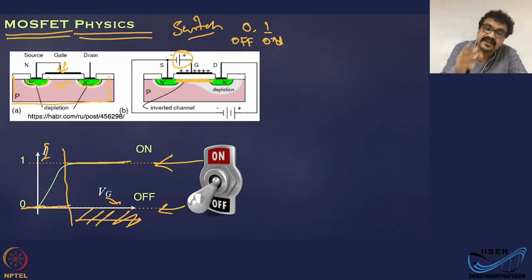That means this is again like a relay where you have conduction, or you have a connection between these two n regions depending on whether you have gate voltage there or not. Depending on the gate voltage, you will get either an on state, or if no gate voltage, an off state.